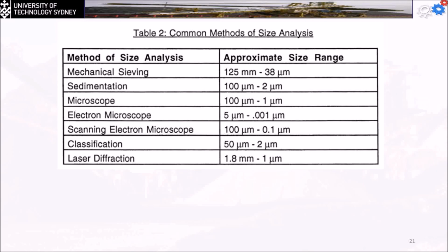So sometimes the sand is standing on the ground with the help of a retaining wall. That's different. The angle of repose measurement doesn't need any support. You simply bring the sand, put it on a flat surface, it's going to repose, and you measure this angle. You don't have to support it with anything. That's a different issue. Okay.